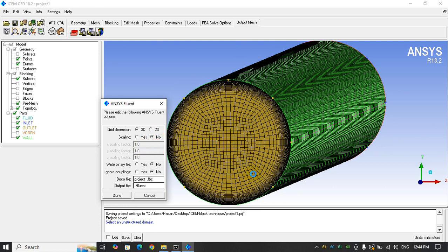Because we created the whole mesh or geometry starting from the 0, 0, 0 point, if you scale the geometry, it won't affect your simulation. This is one of the good things: if you want to have a CFD model, it's better to consider that point as the origin. Maybe in the future you need to scale your mesh, so later you can do it.